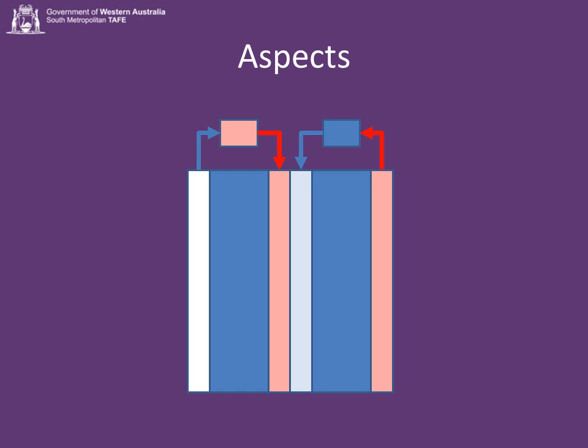In contrast, on the west side of the building, we're taking cold air because those windows are getting cold, because they're single glazed windows, because we live in Perth and we don't know what double glazing is. So these single glazed windows are bloody cold. We're taking cold air out of that building, we're heating it up like crazy, and we're sending it back to the building. So I've got two air handlers. One's cooling, one's heating. I've got the chillers running. I've got the boilers running.